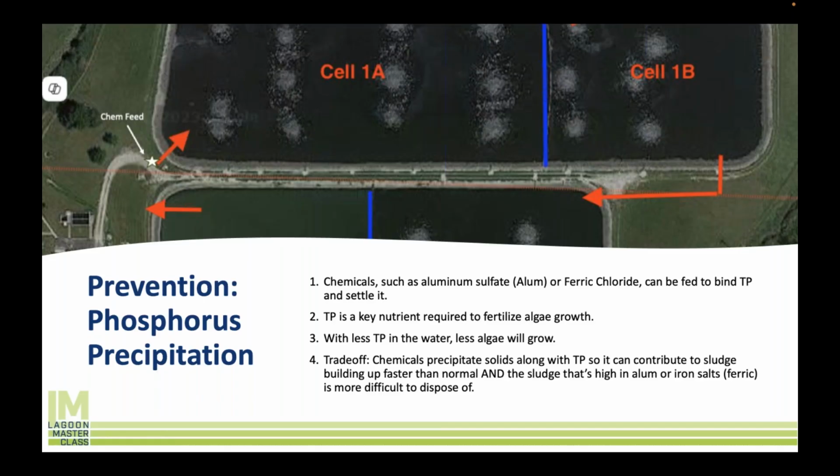it's definitely helping the algae grow, right? I mean, how many times have I walked on a site where I've seen a surface aerator boneyard in the corner where they just pile up all these surface aerators, and the lagoon has 2 surface aerators and it was supposed to have 10 or 5 surface aerators in the past, for example, or you have a diffuser system that has some major breakages in it, right? These things are not helping your algae. They're making your algae worse. And probably you would have less algae if your aeration actually works. So an aeration upgrade might be something of interest.